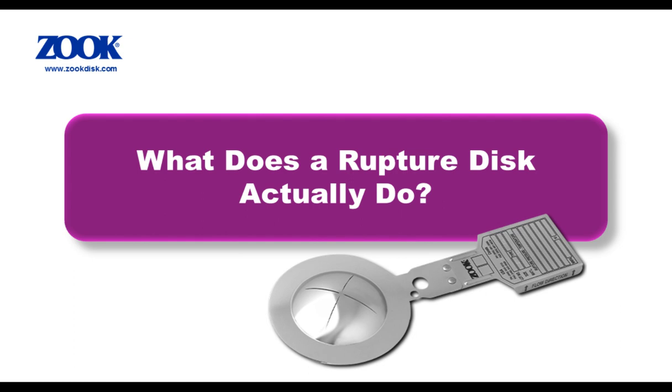What does a rupture disk actually do? Well, a rupture disk is a differential pressure device. A proper rupture disk assembly creates an impermeable barrier in a pressurized system, and it bursts or opens when the differential in pressure across it reaches a designated level. We have a quick video to show you demonstrating rupture disk functionality.